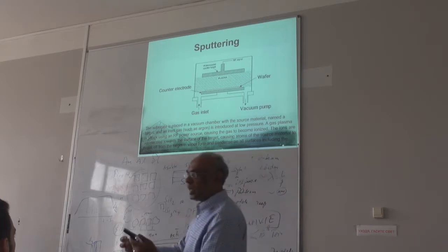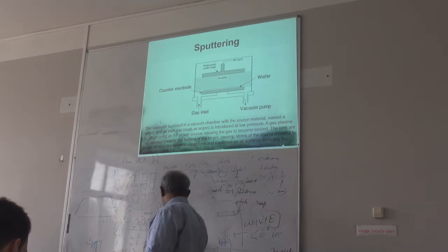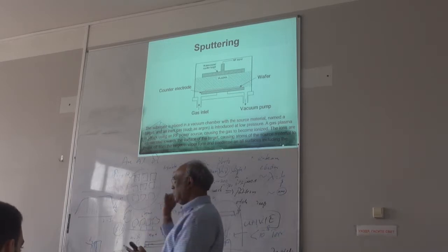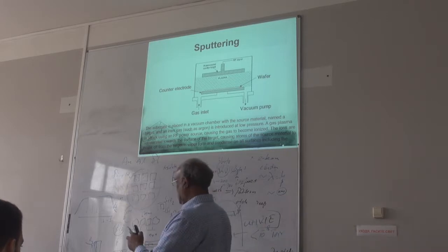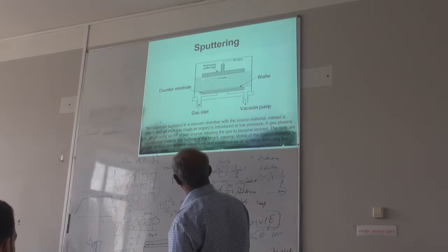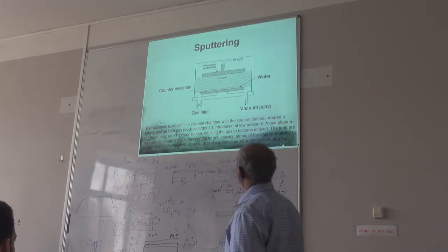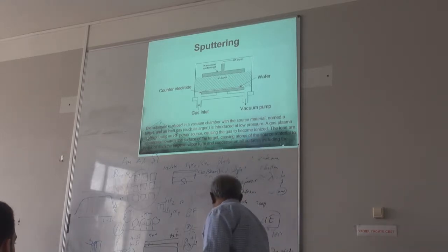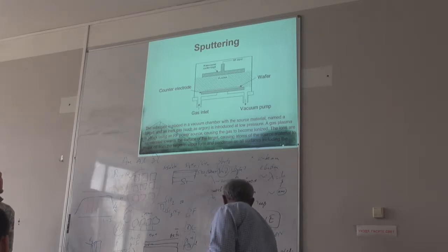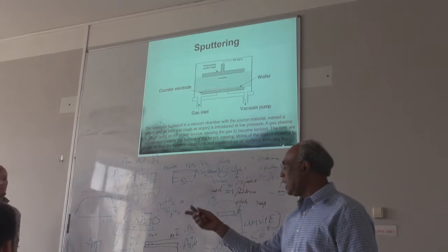Plasma typically has neutral atoms, ionized atoms, and radicals. These ions are pretty fast moving, so they come and knock material from your target, and it will deposit on the wafer, because we have a magnetron so that you can deposit it. That's another way to do this: thermal evaporator or E-beam evaporator, or the third one is sputtering. I think they have a sputtering system.